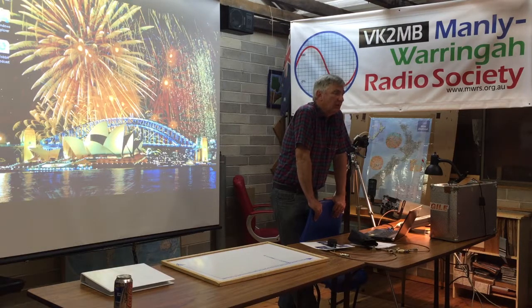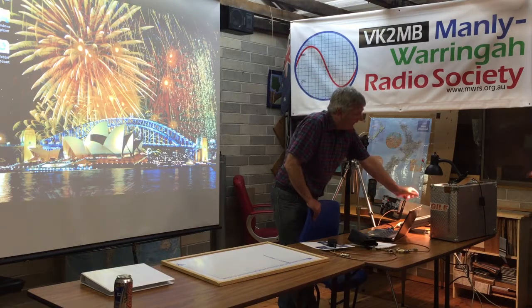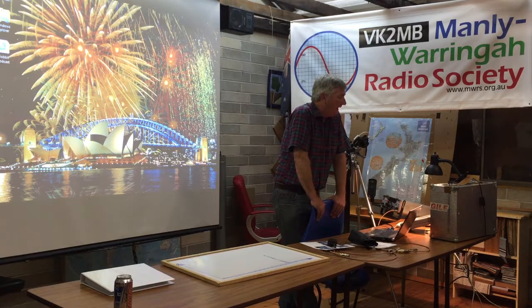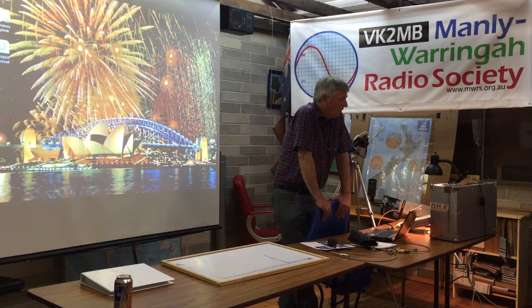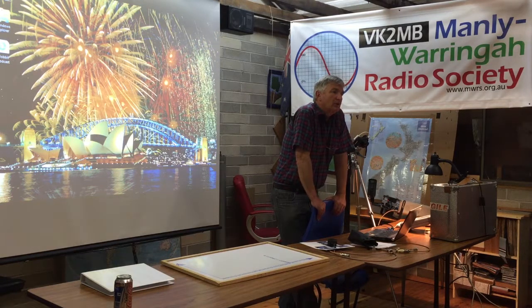Absolutely, yes. With a spectrum analyzer and some form of antenna, it can be just as crude as a bit of wire shoved in here. Or, as I mentioned before, we had a project a couple of years back where we made some shielded loops out of hardline for tracking down noise. But yeah, sure can. Switch off the sun and see if it goes down.